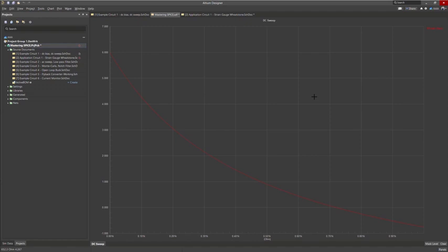And what I want to do, remember, is find the point where I have a difference of 0 volts, because this graph is the difference between those two outputs, Vout plus and Vout minus. So let me go ahead and right click on this. I'll add a cursor to my graph, and I want to find where this crosses, and it should be somewhere around there. So let's move my cursor, and if you look at the bottom left of the graph here, I have my values for my cursor. So visually, you can just look at this.